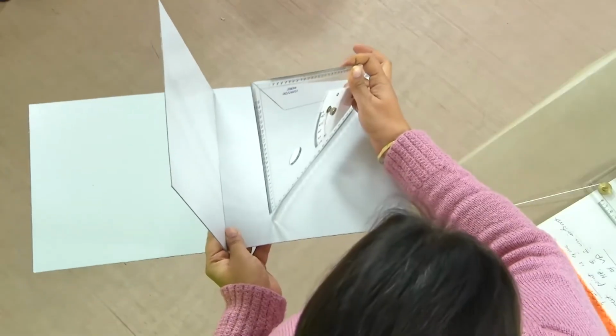What if the plane in question is perpendicular to HP and parallel to VP, and then it makes an angle with VP? So this is how the change happens. Right now it is parallel to VP, perpendicular to HP, and when we incline it like this, it becomes inclined to VP and we see a changed shape in VP, which is its vertical trace. So let us see the steps of how to draw the orthographic projections of a plane which is making an angle with one of the reference planes and is perpendicular to the other, in a stepwise manner.